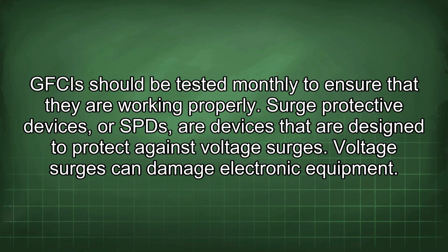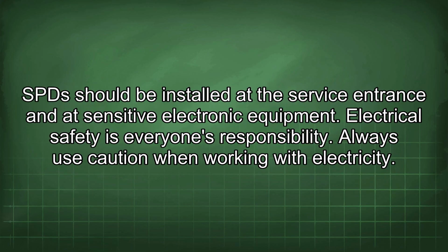Surge protective devices, or SPDs, are devices that are designed to protect against voltage surges. Voltage surges can damage electronic equipment. SPDs should be installed at the service entrance and at sensitive electronic equipment.